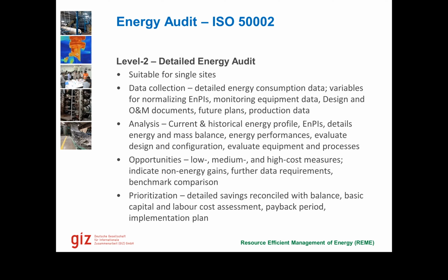That would mean that we don't need any time, or even less time, to heat up the water in the machine. Because we need less time to heat up the water, our batch time reduces by 5 minutes or 6 minutes or 10 minutes even sometimes. So if a batch takes 30 minutes, and we have a cold wash, the batch time reduces to 20 minutes.